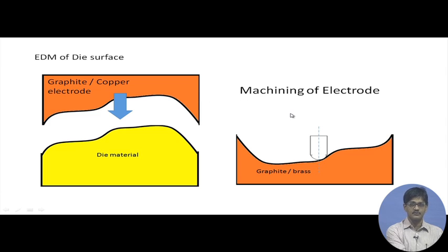Of course, there are other issues with these materials, but at least they are machinable without causing that kind of tool wear. So, if this is the inverted electrode which was used previously, we can use a ball-ended milling cutter on a 3-dimensional machining center and cut it out. So, here the application of 3-dimensional machining is very much required.